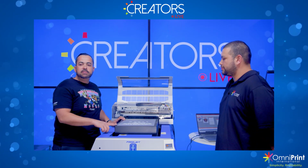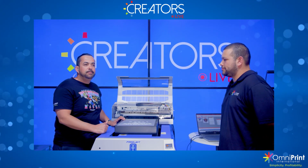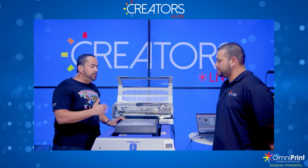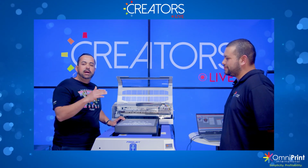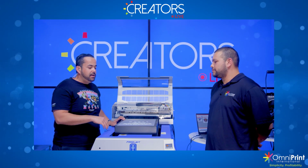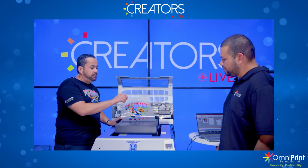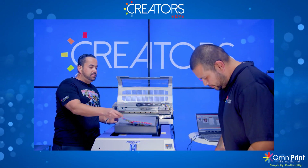What are the advantages of having this thing? Number one is you can print faster because the ink is going to dry, right? So if you don't want to have your high DPI settings, you can use the heated platen and it'll hold the film in place while you're doing that, right? That's important.